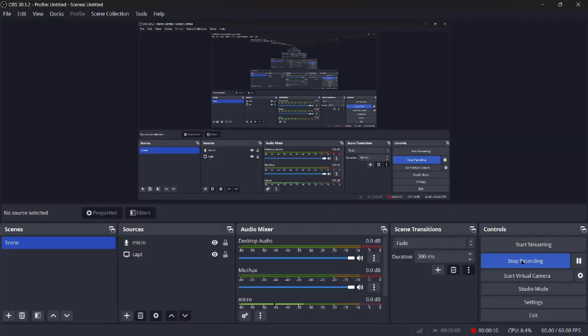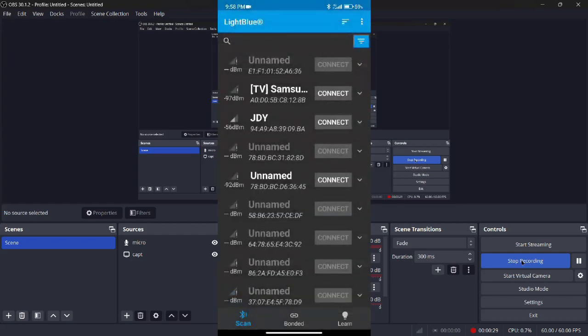Now I will show you how to determine the distance between the Bluetooth module and the phone that is connected to it via the RSSI value. So open again your LightBlue app and place your phone 1 meter away from the Bluetooth module. You should read like 56, 55 RSSI. The RSSI is found under the signal strength indicator.